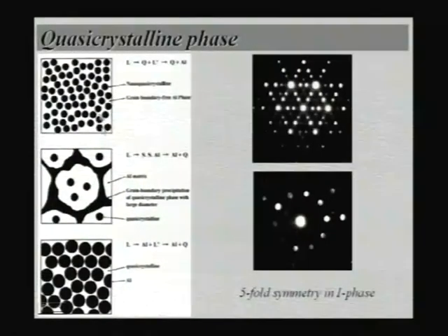After that, in a number of aluminum alloys people have observed quasicrystalline phase, and now people do not want to use this kind of quasicrystalline phase as a single quasicrystalline phase. If it can be obtained in a nano-quasicrystalline fashion, one can have much better properties. So people are looking at such nano-quasicrystalline phases, and these can be obtained in a number of microstructures. For example, you can have an aluminum matrix with nano-quasicrystalline particles. You can also have some grain boundary precipitation of quasicrystalline phase in an aluminum alloy. You can also have a quasicrystalline alloy in which aluminum nanoparticles have been precipitated by choosing a proper composition.